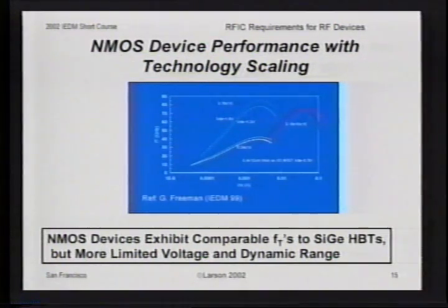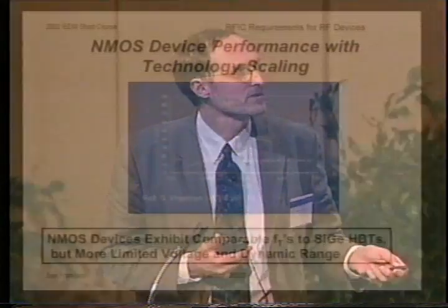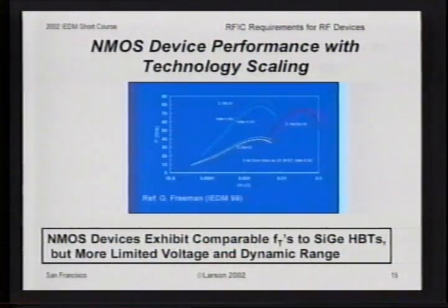Finally, for applications in the 1 to 5 gigahertz range, which is where 99% of RFICs are today, almost either of these technologies is adequate. So from a mass commercial marketplace perspective, both CMOS and bipolar technologies are now at the place where they can address pretty much all the system issues. There's a dynamic range issue, or breakdown voltage issue, with MOSFETs that I'll return to in a second.